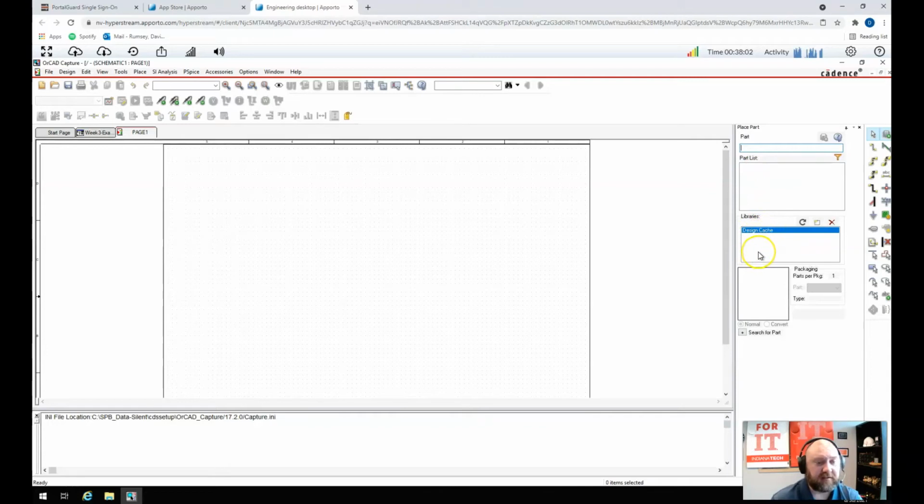And that's because we don't have any libraries installed. The way this software package works is that we have to install the libraries. Now, there are already a lot of libraries that are pre-defined for us, but the reason it doesn't install them all at the beginning is that there are a lot of libraries, number one, and they can actually slow things down because basically you're generating PSpice models and loading that in for all sorts of parts that you might not want to use. And typically, in industry, you either have to use a library that's provided by the manufacturer of the chip, or some companies actually create their own PSpice models when they're actually doing design and simulation.